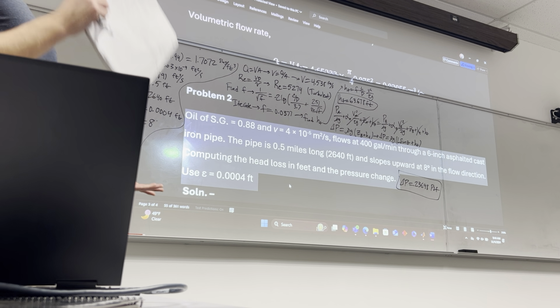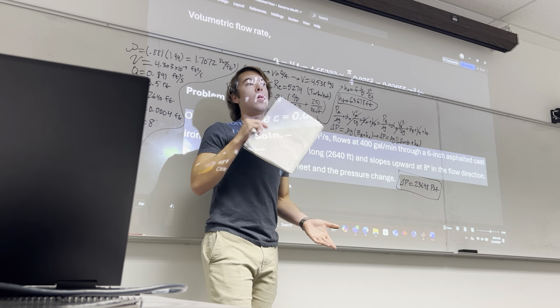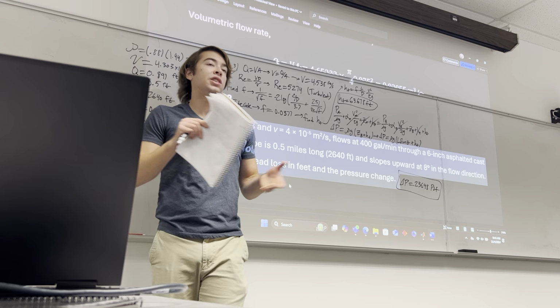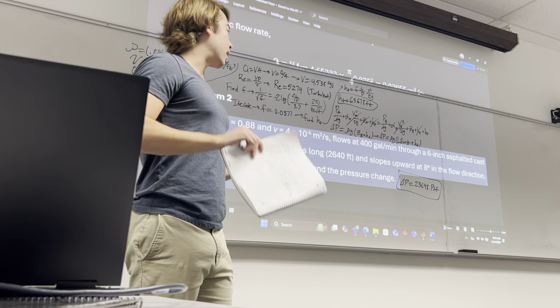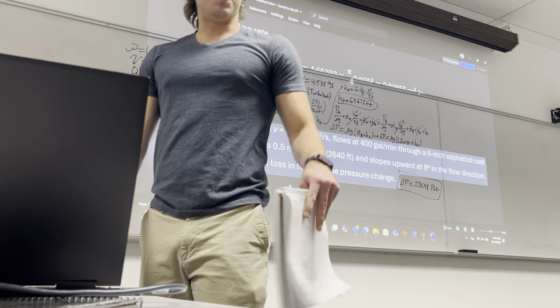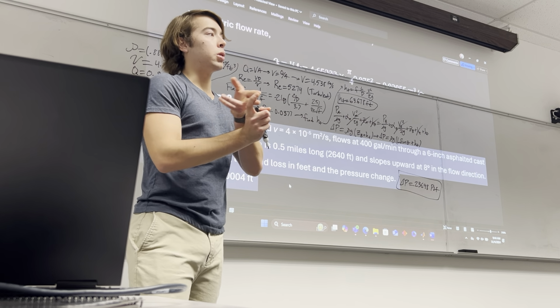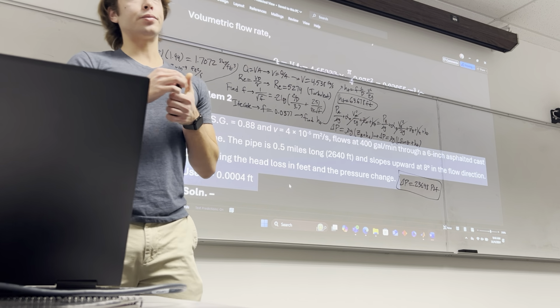Anyway, any questions there? Everybody all good? Everybody cool? This is not that high level of a concept. Just know when to apply the equations, and really your step one for a lot of these problems should be trying to find a Reynolds number and a velocity value to get that Reynolds number. And then from there you can make a lot of stuff happen pretty quickly.